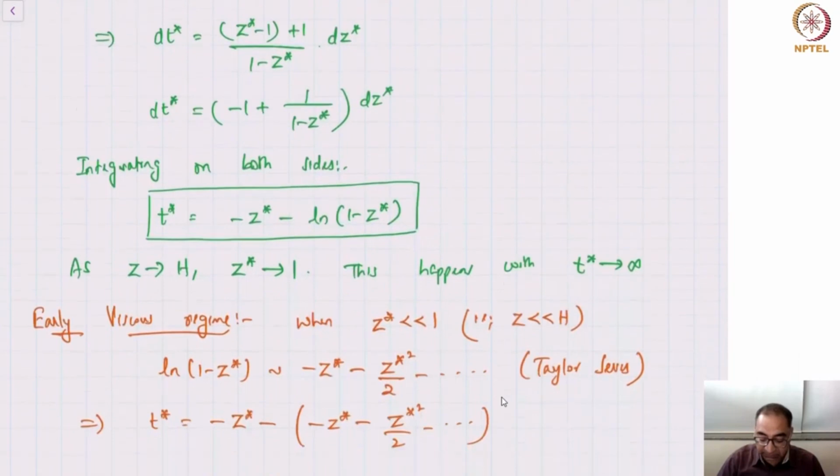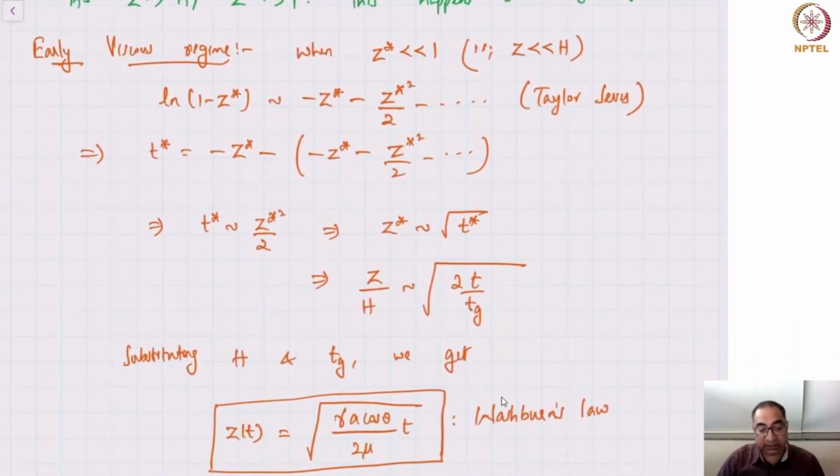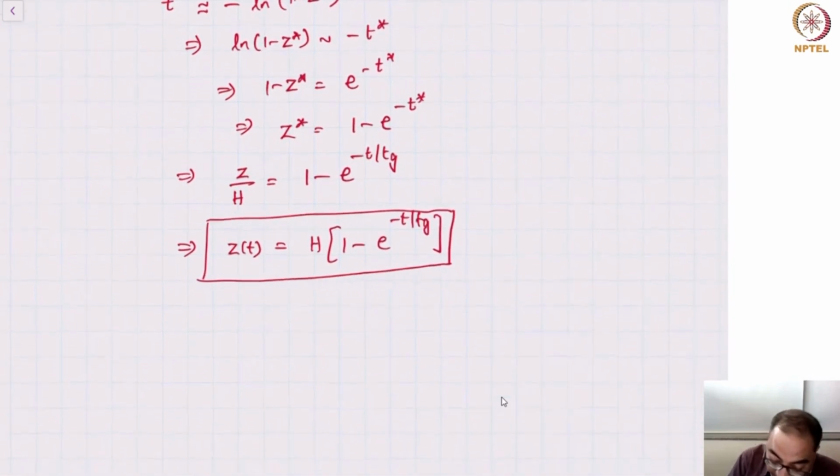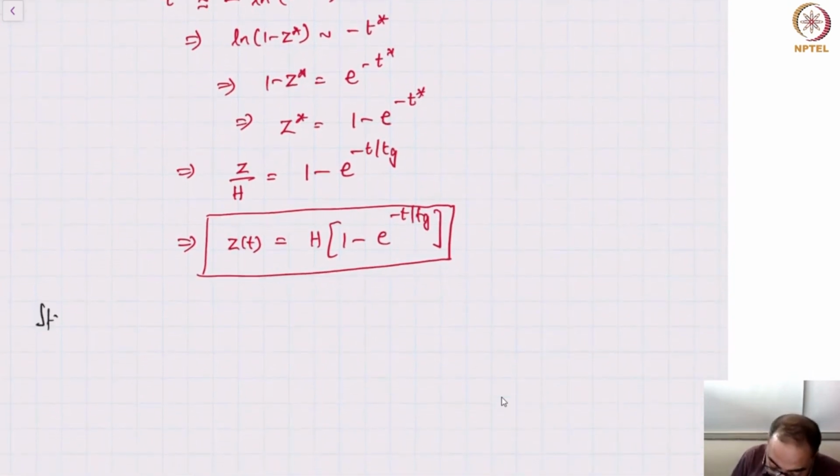And once viscous regime becomes important, we can again divide them into two regimes. We have the Washburn law, where the column height slows down, it grows, but it continues to grow like root T. And finally, we have an exponentially decaying regime. Okay. Now you can further say static regime is finally the last regime in some sense.